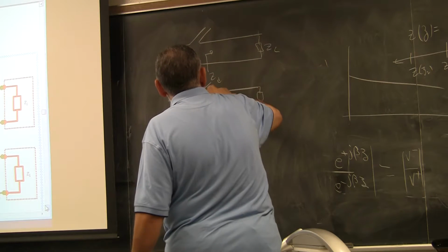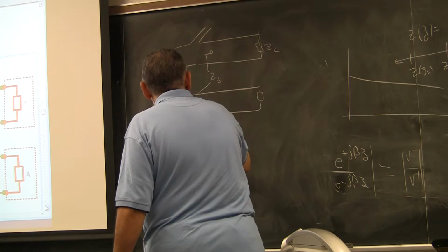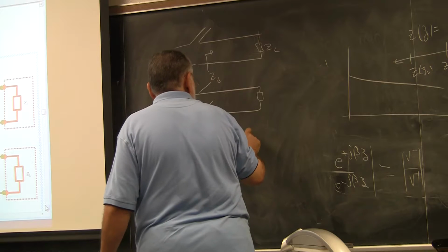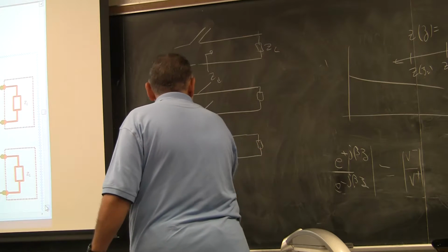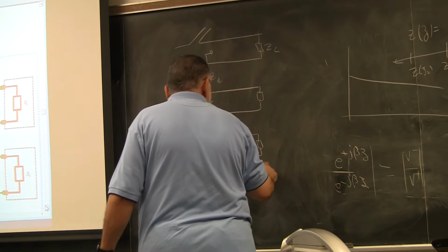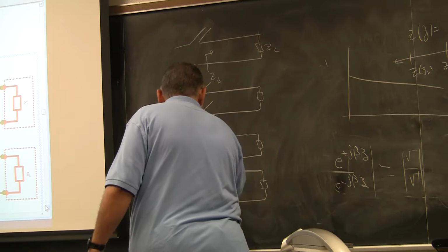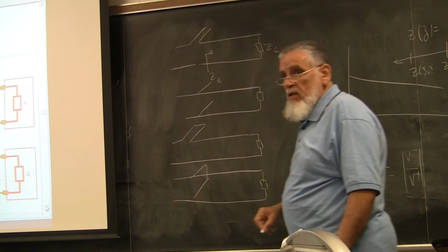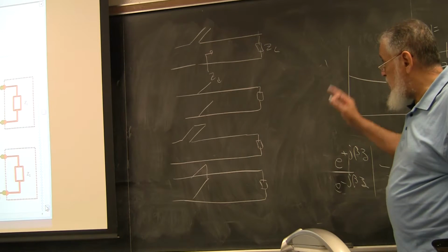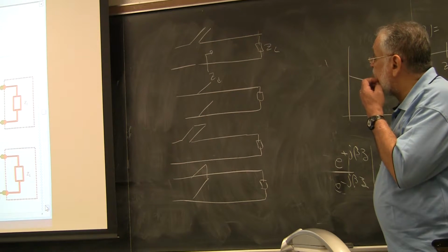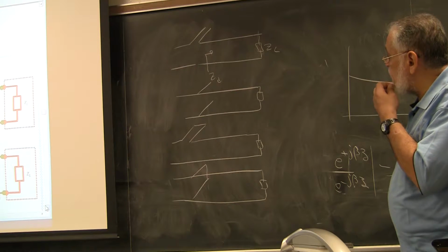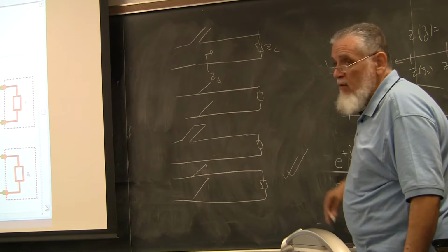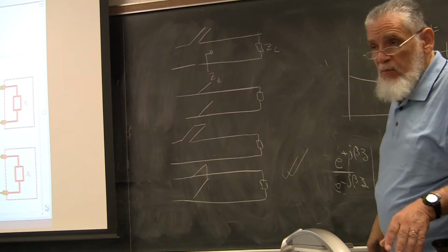And in this case here, the stub is open circuit. I can do the same thing with a series stub that is shorted, or a shunt stub that is shorted. You have 4 mathematical solutions, and you can design for any one of these 4. Now this one here is the one that we prefer practically, but nevertheless,